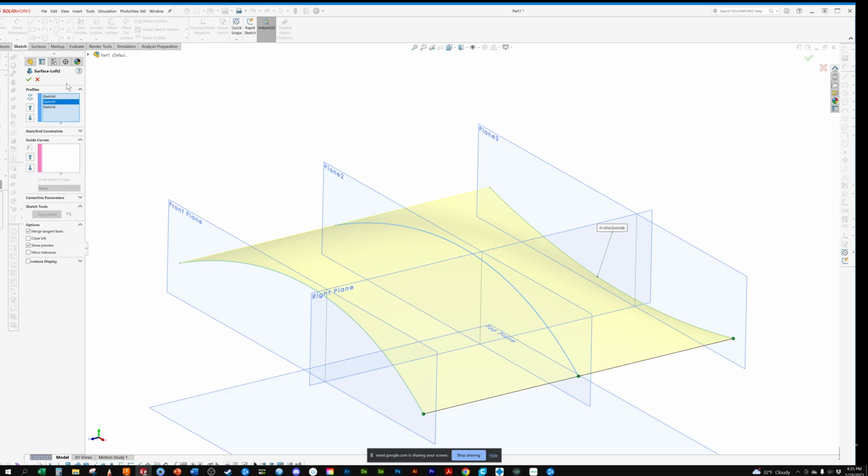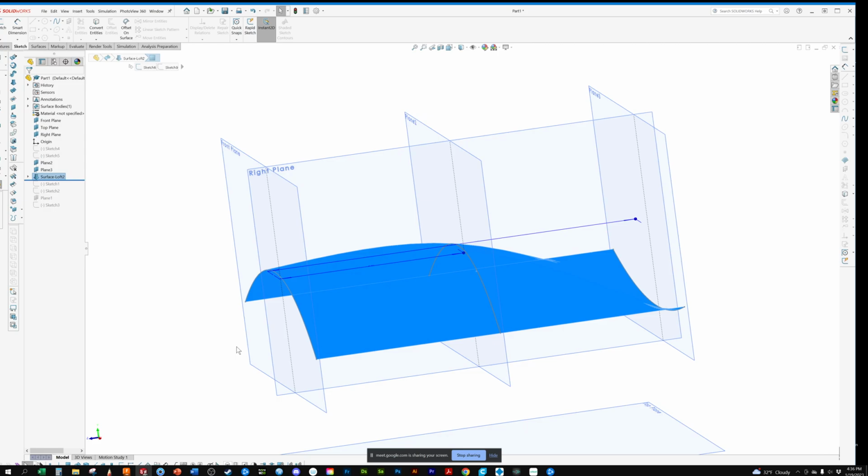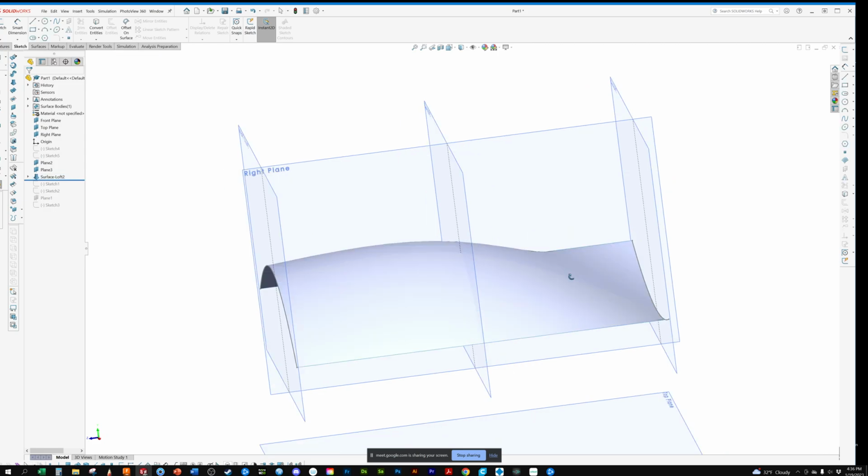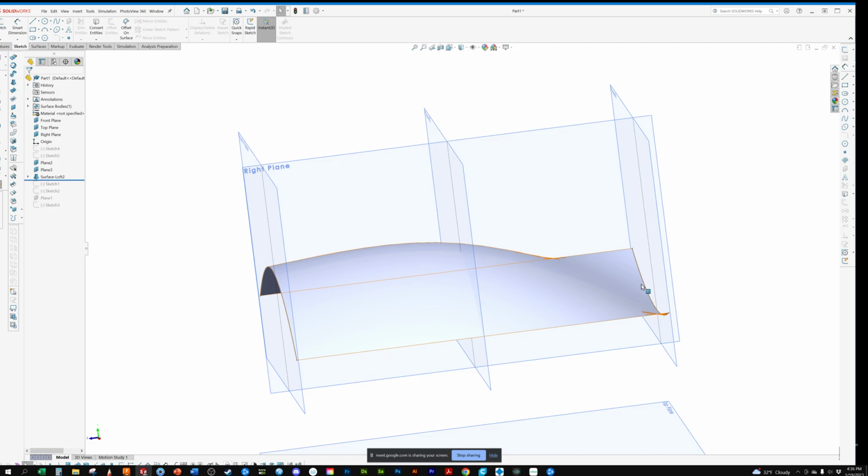So now I've got that control. Because this curve is the same as this one, this shape stays the same from here to here. And now I've moved the transition point of blending from this curve to this curve profile to the middle of there. So I still don't have control to the outside edges because it's still going in that straight line. Questions?